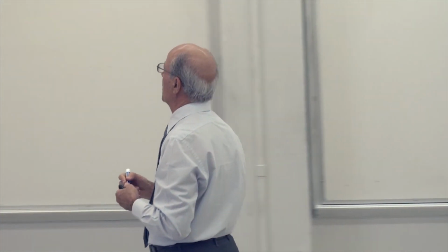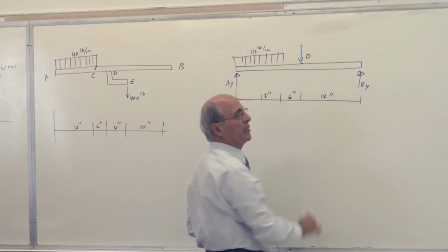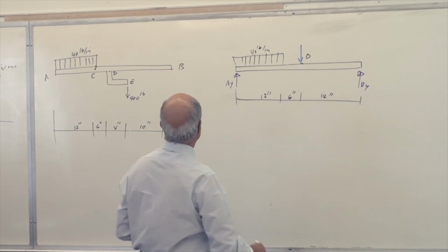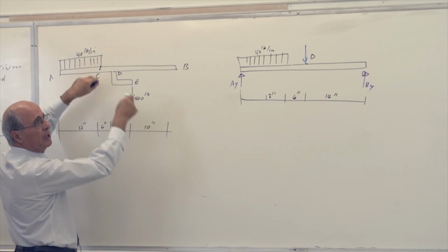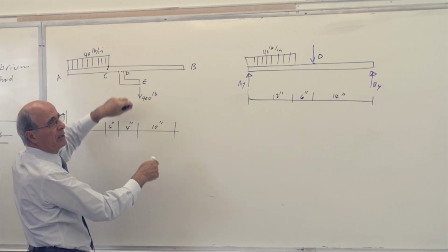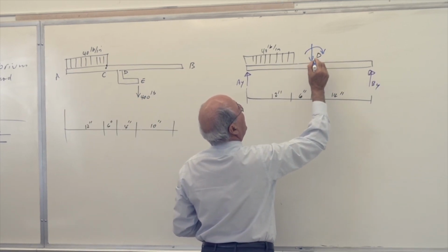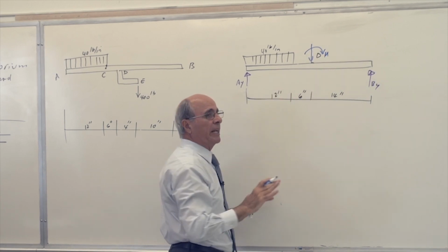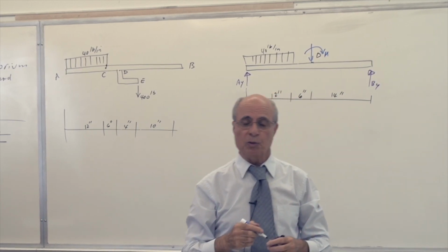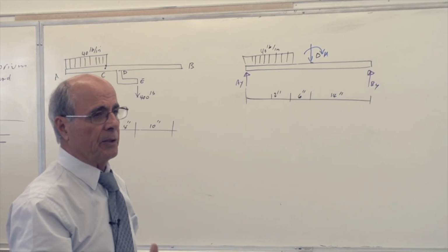So this is understood, exactly what you learned in statics. The load goes itself. But look at the couple, which way is it moving? Put your hand here. It is going like this. Is that correct or not? So there is a moment here, or a couple, and this is your MD externally. These are all, again, external. The idea is to find the internal one, which is the shear and moment diagram.